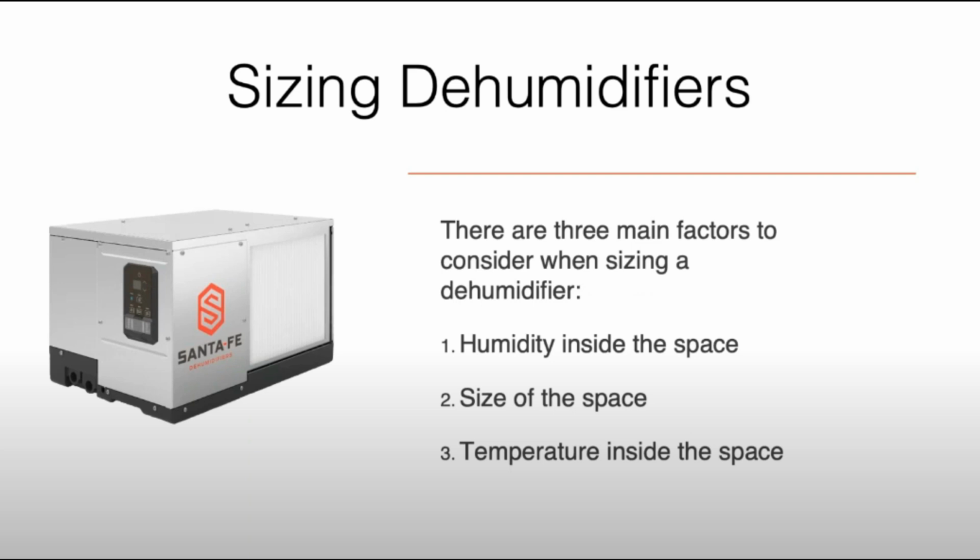The temperature inside the crawl space is the other factor we need to consider. Remember, for every degree the temperature goes down, the RH goes up 2%. Also, for every degree the temperature increases, the RH goes down 2%. RH and temperature give you a dew point, and that really lets us know how much moisture is in the crawl space. Another important thing to note is the fact that it's easy to undersize dehumidifiers, and it's hard to oversize them.